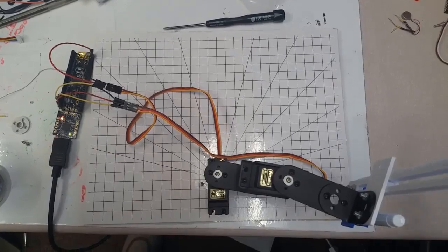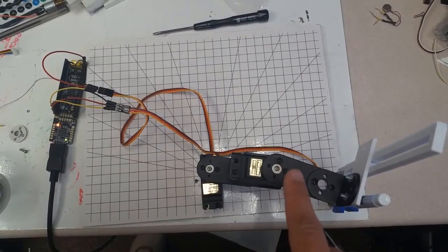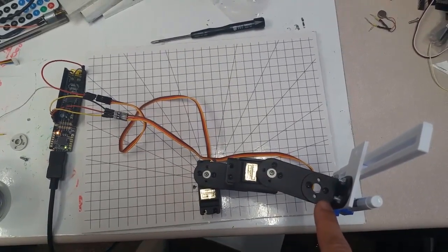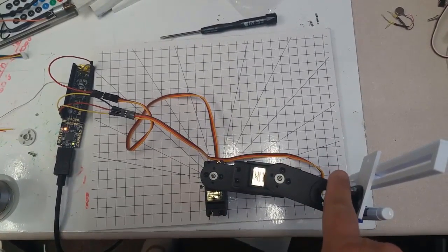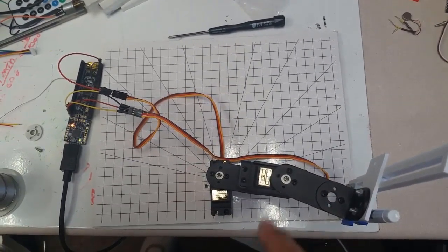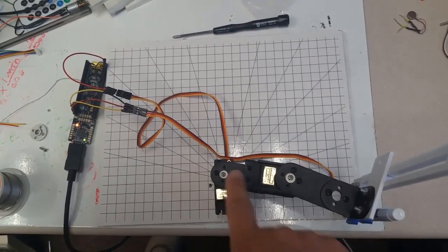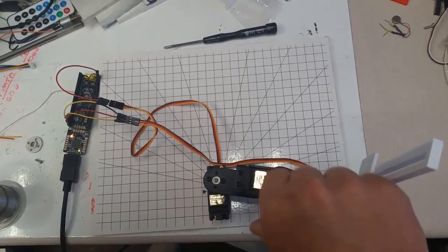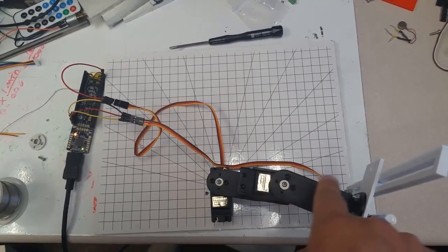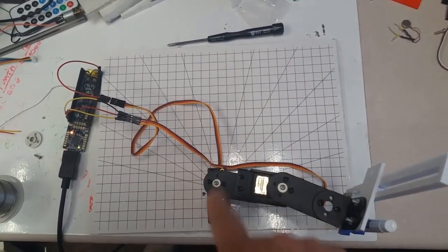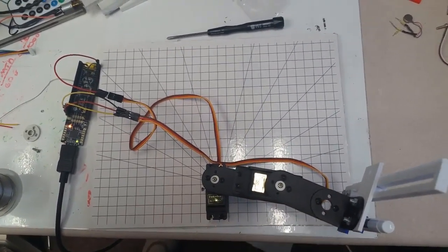When I click program, this is the result. My first servo is turned a little bit too far negative, and my second servo is also turned too far negative. When I have this correct, it will be straight out. Now, if you run yours and it's nowhere near being straight out, first unscrew these two screws and rotate the horn, and then pop the horn back on and screw it down so that it's at least close to being horizontal along this, which is our x-axis, our x0 base frame axis.